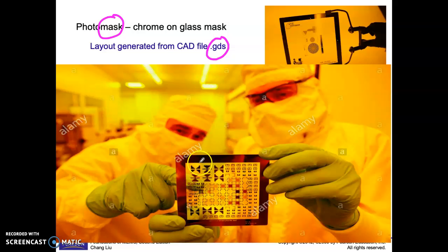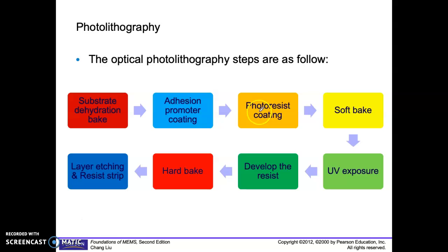Let's say I do a piezo energy harvester. So this is all your design. You're going to pack it inside the chrome mask. This chrome mask is fabricated outside, so the cost is around like 1,000. So you need to compact all your design at all area because this is quite an expensive mask. This will be what we call photo mask.